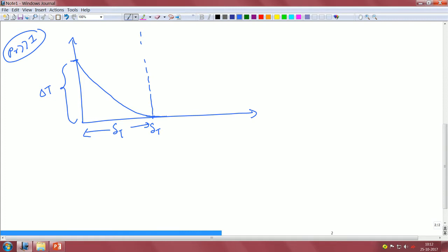So that is the temperature profile, correct. Here in this particular zone, in the driving heated layer, this is the driver, because beyond this there is no temperature gradient, it is T infinity. So, the temperature decays naturally, it takes heat from the wall, and the decay amount is basically 0. That means you reach T infinity after the delta T is over. That is standard whatever we know about boundary layer.